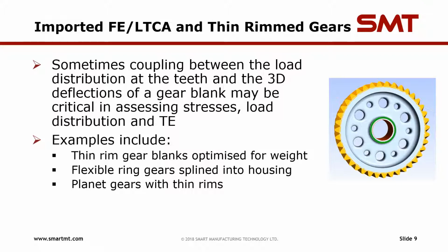Another area we're looking at in some detail is thin rim gears and improving our FE and LTCA functionality. For example, such as the ring gear I showed previously, where you've got quite a thin rim and quite large deformations in that gear, we think the tooth contact analysis can be improved in this particular case.